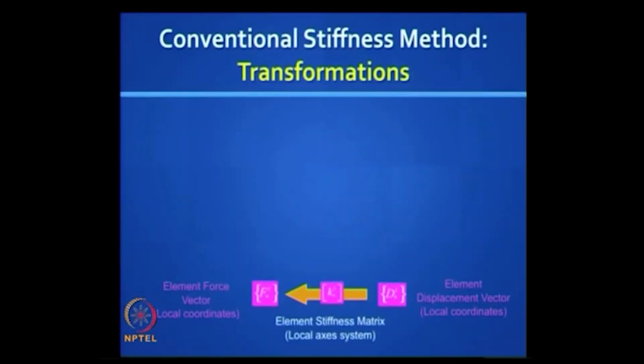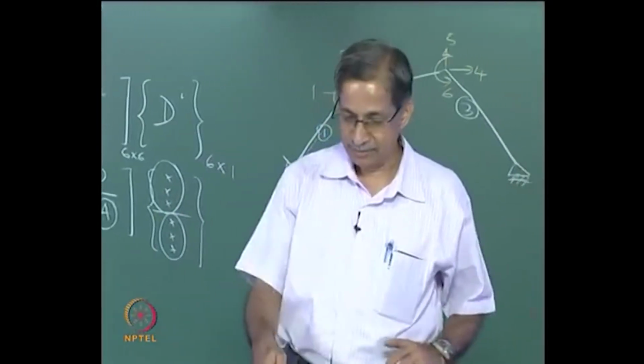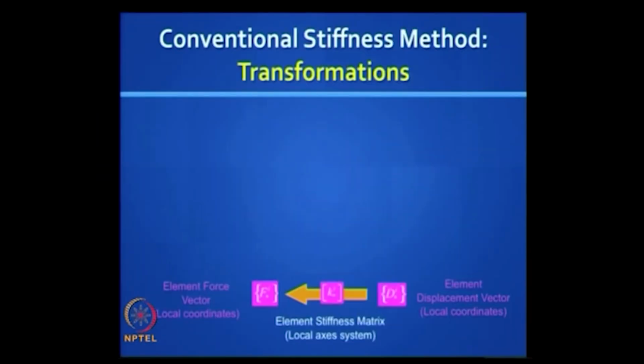Okay. So let us take this one picture, it is a beautiful way to understand it, I want you to draw it. I am going to draw a playground with 4 corners. At the bottom line you see how I have done it, it is very easy to do it. I am putting the forces on the left side, the displacement on the right side, right. So the first transformation that I have is the element displacement vector in the local coordinates with the star.